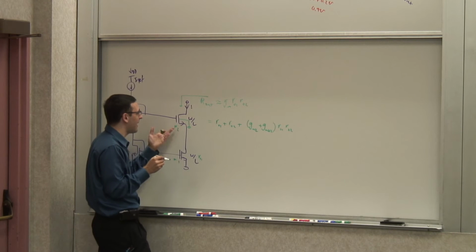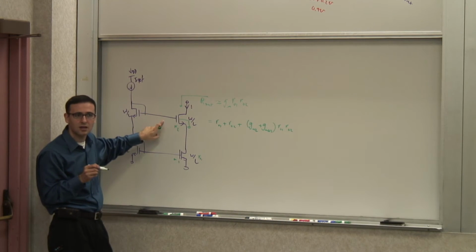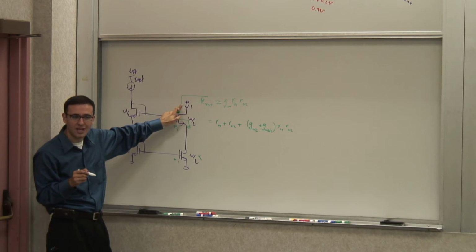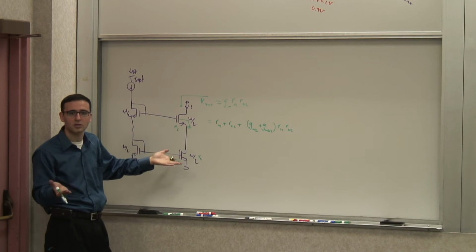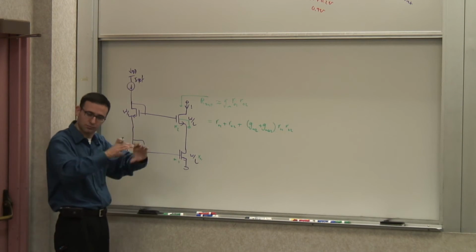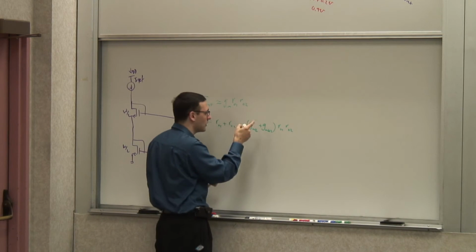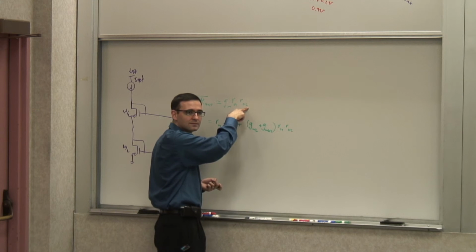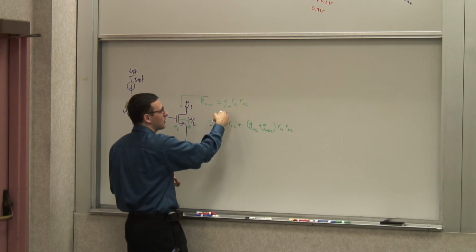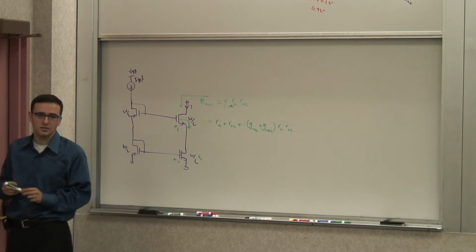And in this case, this is connected in a common gate topology, right? The gate is at a constant voltage, the input is here, the output is there. And in the common gate topology, we saw that gm and gmb work in tandem, work together, because both transistors were connected in a similar way. So if you remember, gm RO1 RO2 is good enough. But if you want to do it accurately, it is gm plus gmb, with gm1 and gm2 for the cascode transistor.